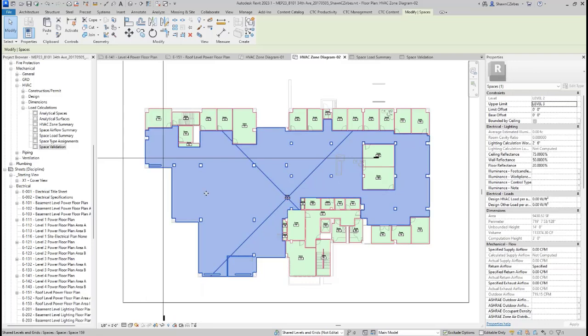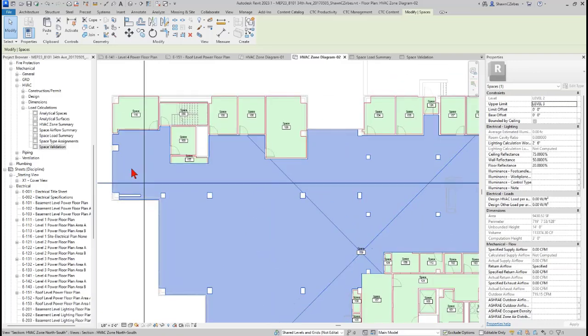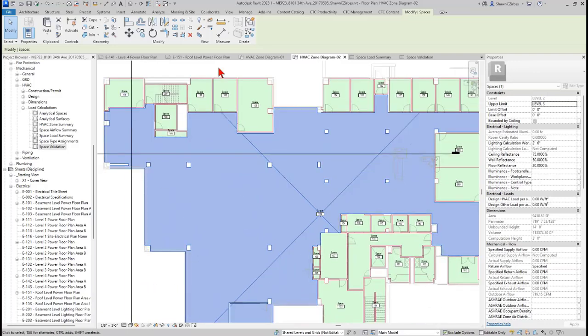It's going to heat and cool. This side's going to get a lot warmer in the afternoon than this side is. This side's going to be a little bit warmer in the morning, right? So I probably want to divide these up into little micro zones inside of here.